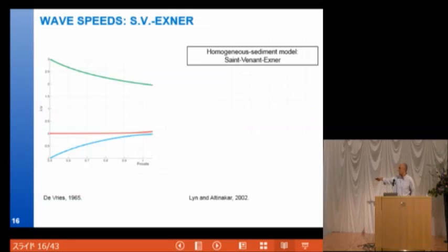There is other information that I would like to remark here. This downstream propagating wave, the fastest one, is translating downstream all information concerning bed change variations. And the same applies to the one propagating in the upstream direction. While the red one is mainly related to the bed.